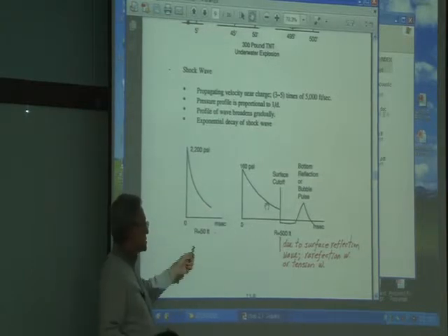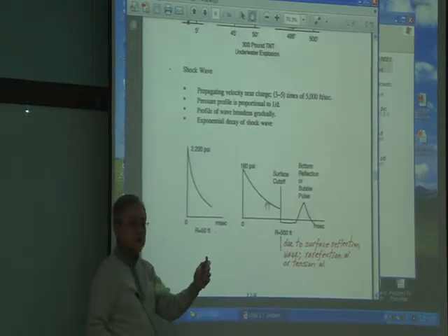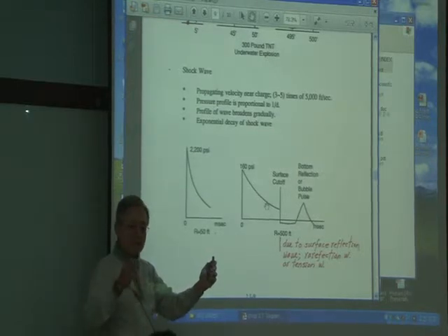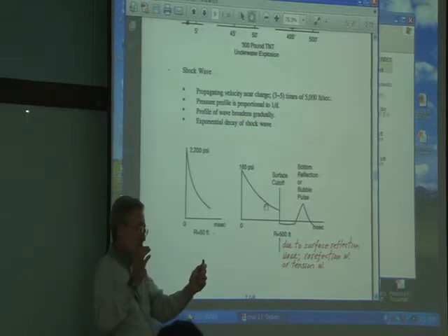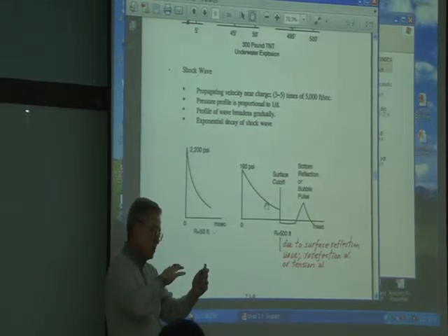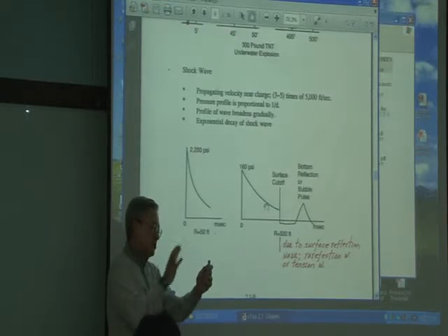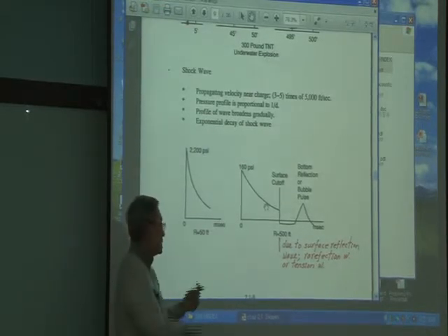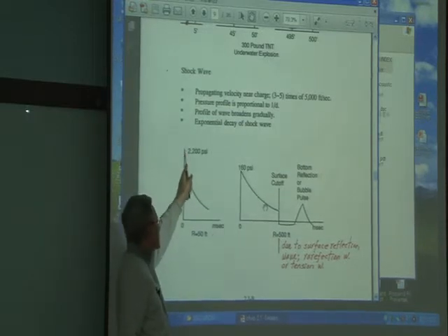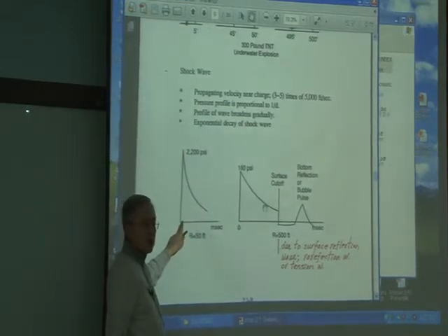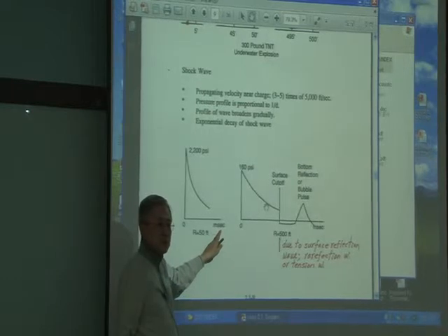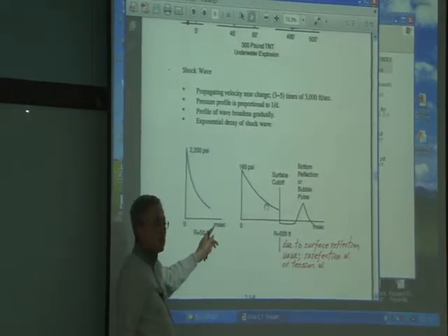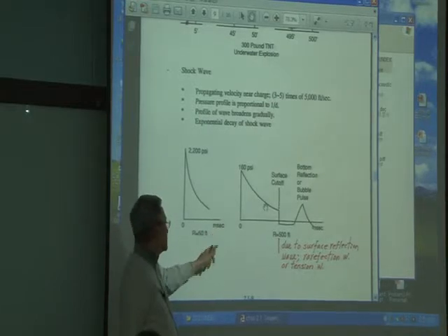Standoff distance, exponential decay. I'm staying at this one point, that's the target point, and your explosion point is right here. This is the distance. Okay, I'm standing here. Then at the time of explosion, the shock wave will broaden up, propagate in the radial direction, then hit the target and pass by. This is the profile, going up and down. This is where the shock wave hits the target. Okay? Then we are dealing with milliseconds. Everything will be done in 3 or 4 milliseconds, then done.